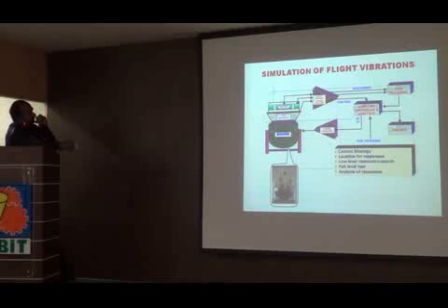Also we need to give the input, so we use something called a controller. It gives digitized data. This data is amplified by the power amplifier, so that the voltage and current demanded by the shaker are met. And this being a closed loop, it follows for every few milliseconds of operation depending on the range that we choose. In the closed loop, we strictly monitor that the level we need to give on input is going, and the responses are also monitored at critical locations.